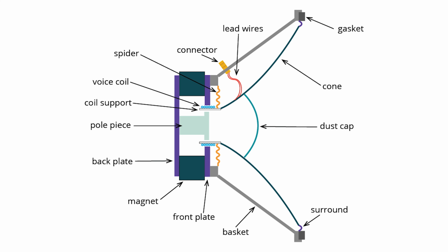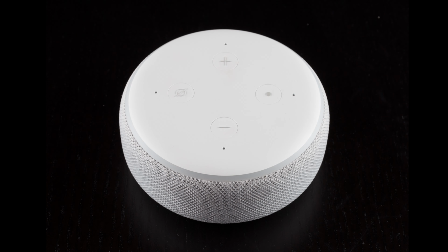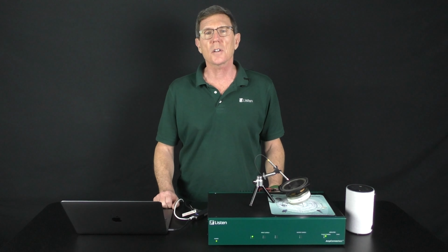Transient distortion is caused by loose particles becoming trapped under the diaphragm or dust cap and rattling randomly with the movement of the voice coil. It can also be caused by loose buttons or other rattling components. If your devices start failing distortion tests, it's really valuable to know whether you have a rub and buzz or a loose particle problem. This tells you where to look for the root cause so you can fix the problem quickly without incurring too much downtime.